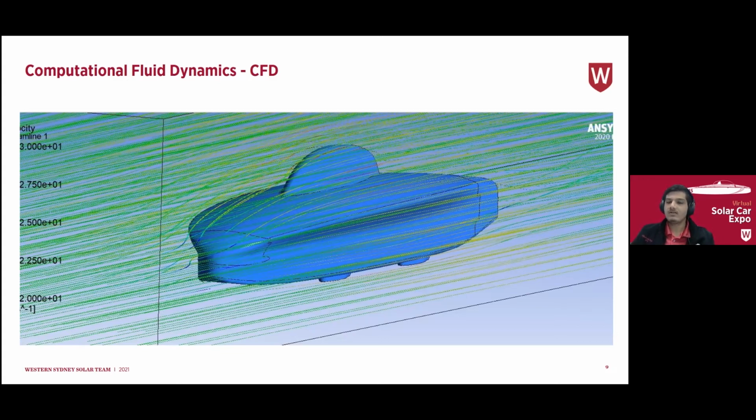But the important thing to know about a lot of aerodynamic studies is that a lot of complex interaction occurs very close to the surface of the object in what is called the boundary layer. This is why your mesh also needs to be incredibly fine in the few centimeters directly above the skin of your aerobody. Once you have a mesh, you can specify your boundary conditions.